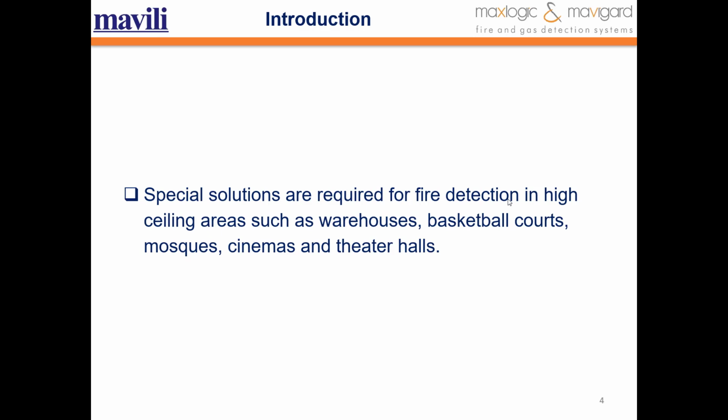Special solutions are required for fire detection in places with high ceiling areas such as warehouses, basketball courts, mosques, cinemas, and theaters. Optical smoke detectors, which are frequently used in spaces, go into alarm when the particle density in the photoelectric cell reaches a certain level after the smoke caused by the fire reaches them. In places with high ceilings, it will take time for the smoke to rise a certain height. So, it will be late for the optical smoke detector to detect fire.